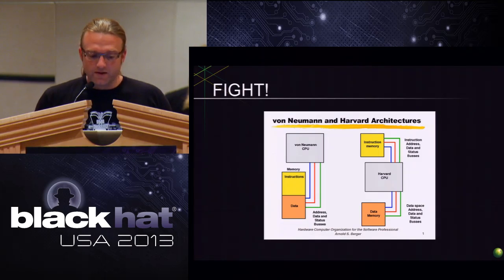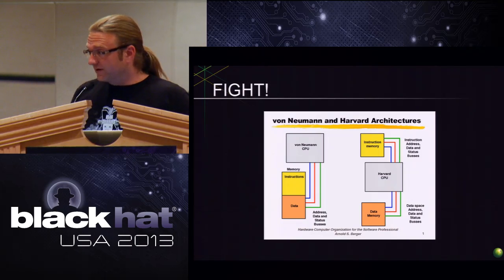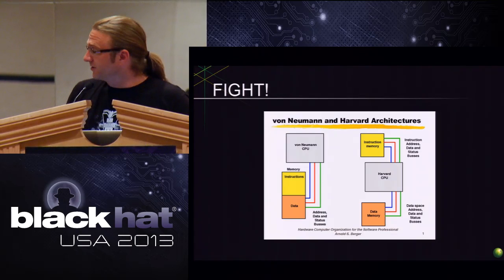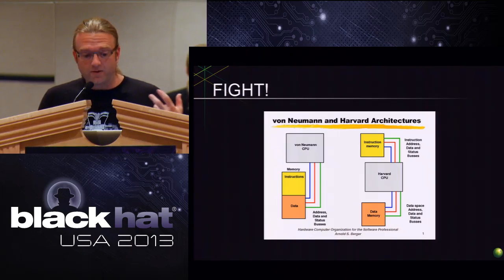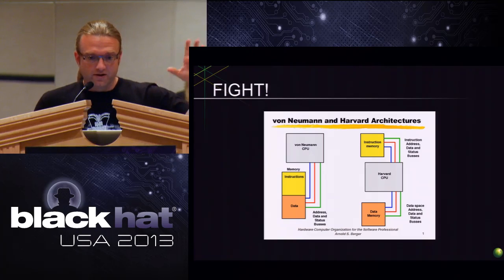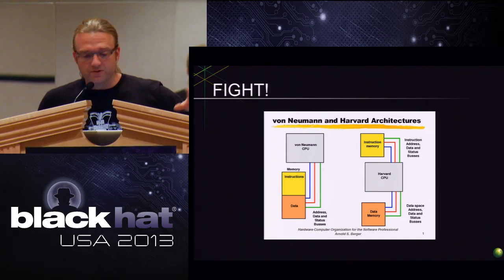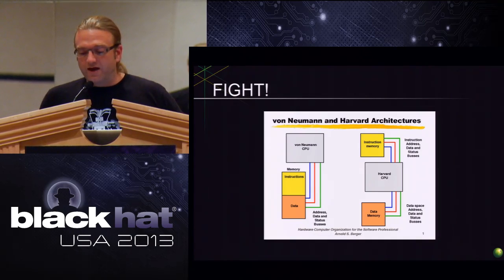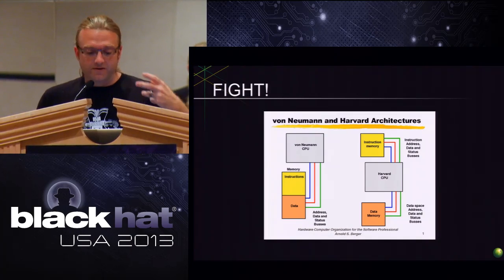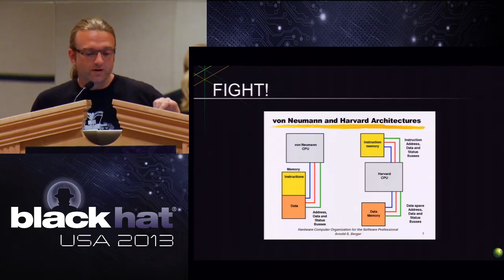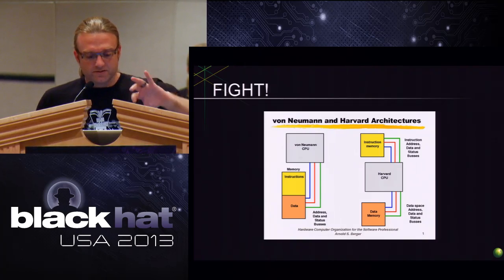And we have Harvard. So when we're dealing with x86 or old ARM or things like that, we're typically looking at von Neumann architectures. When we look at von Neumann and how it works, we're used to having a code section and a data section. We're used to the CPU being able to grab between them. You may have tricks like NX and stuff, but that used to only be software. Now it's software and hardware, but it's an add-on.